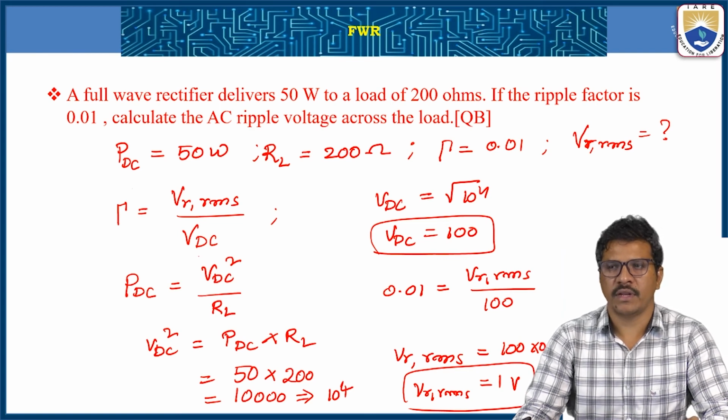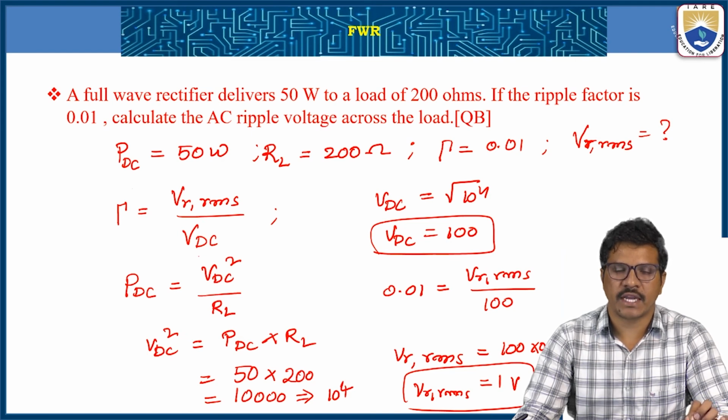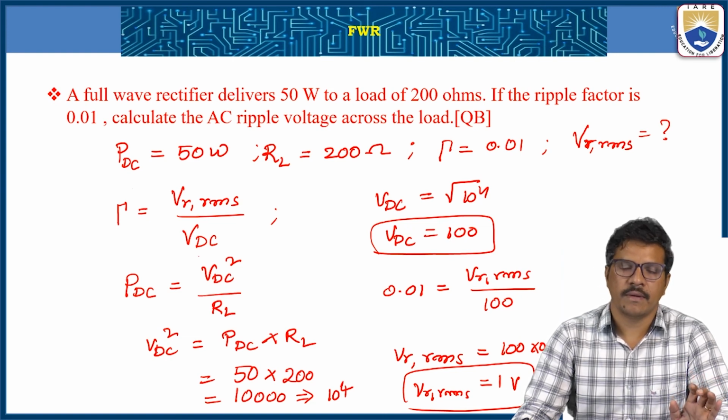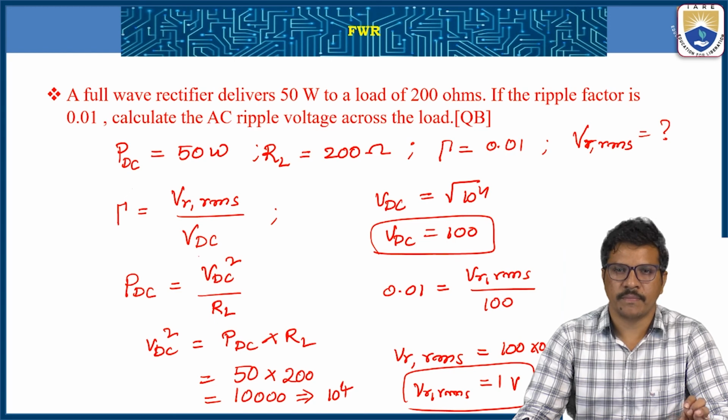But once again, I repeat, remember carefully, find out the maximum voltage of the secondary voltage. In this lecture, I discussed the full wave rectifier. So always think about what the maximum voltage is in the center tap transformer. You must consider that the secondary voltage is divided into two halves. That voltage is substituted in the formula for the maximum voltage Vm.